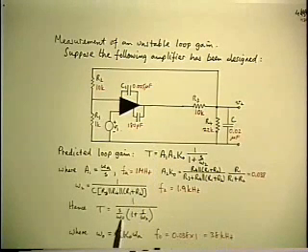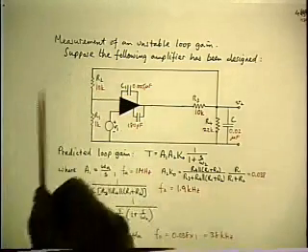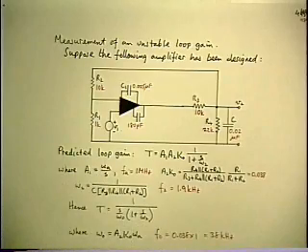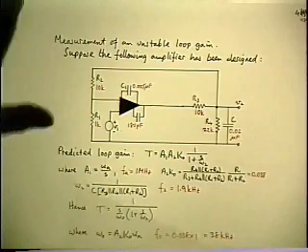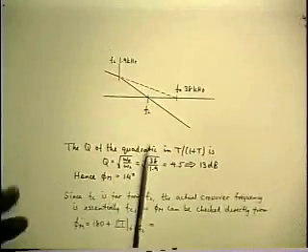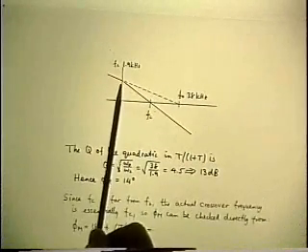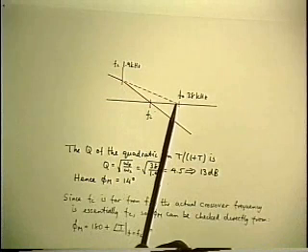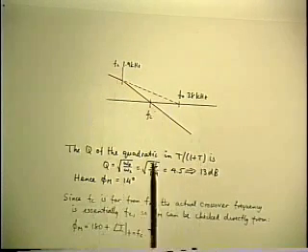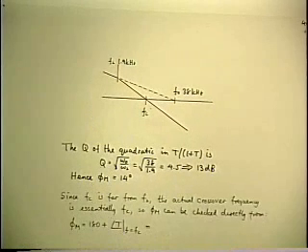And the result, once again, is a loop gain that has an initial single slope, because we still neglected the flat part of 0 frequency, and it has a second pole. And since the only difference is the numbers, the only difference in the asymptote graph is that now the second pole comes in before the extrapolated crossover,